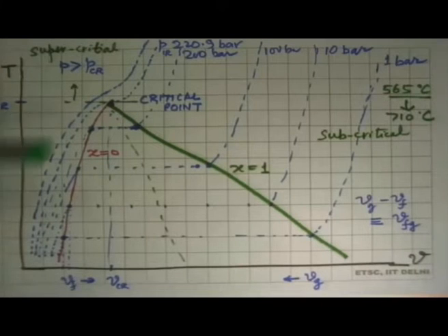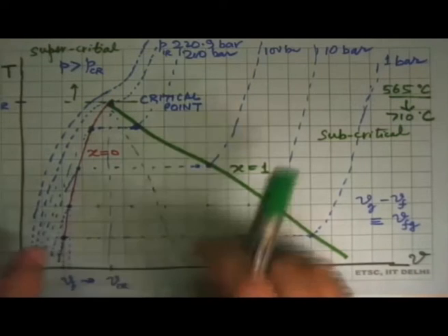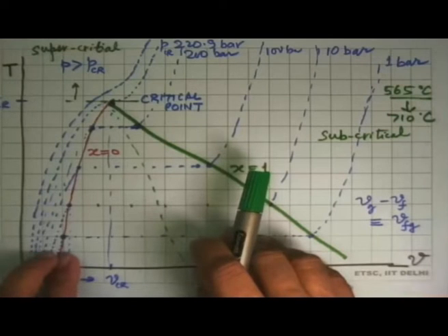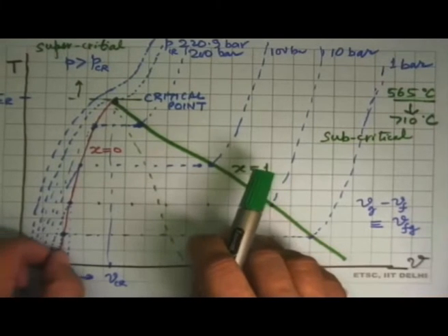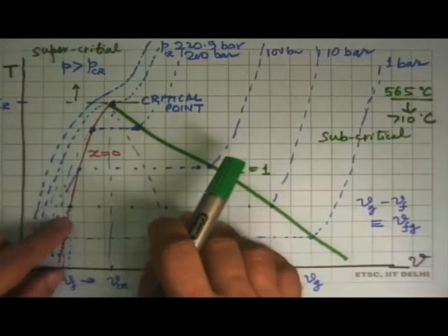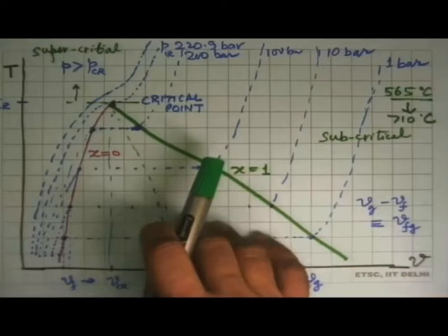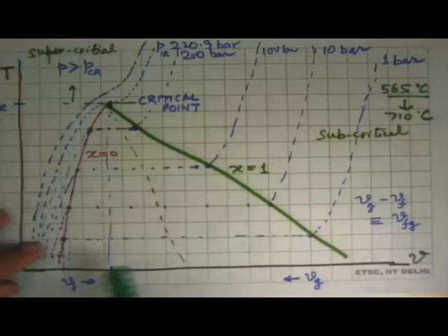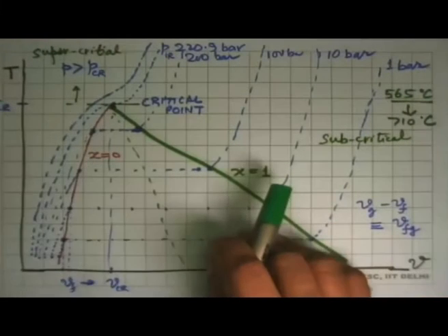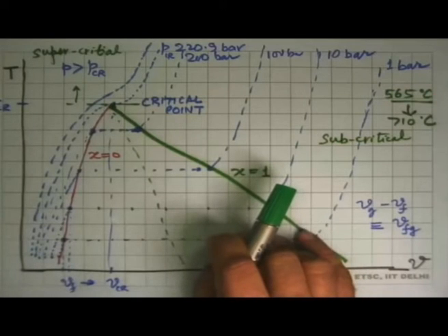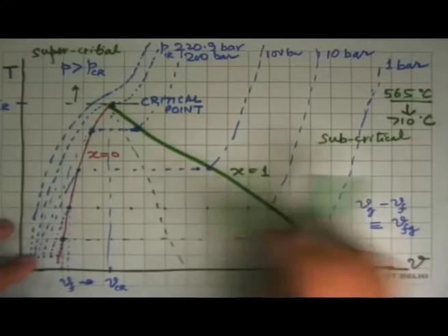So the upper limit of some sort has been set in the properties. As I'm saying, all of this is a huge exaggeration. In the notes, I've given some plots where all of this just becomes very, very small. You can see that in books also, that the effect of pressure on specific volume is very, very small. So as an approximation, one can even say that water at 40 degrees Celsius and 1 bar has the same density as saturated liquid at 40 degrees Celsius.